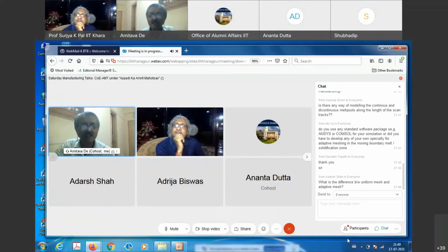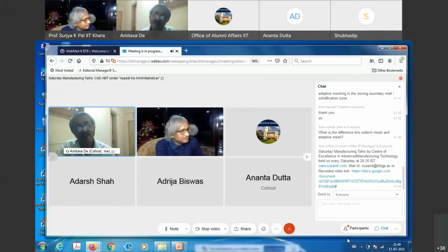So it is increasing the time a little bit. It is just dumping the fine mesh data, giving the interpolated data to the coarse mesh where it was just there before the current time instant, and moving forward. So imagine yourself, you are a fine mesh, you can carry a lot of fine granular information, but you are traveling all through. All around you, the rest of the mesh is getting adjusted so that the total number does not change. So this is the trick.